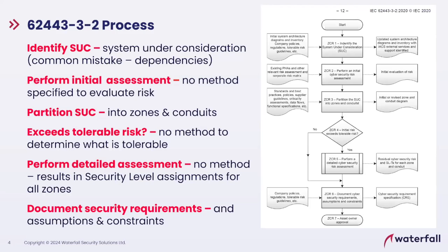Isn't it great? The problem is if the OT systems depend on the IT Active Directory, and the IT Active Directory is crippled in a ransomware or some other attack, we can't log into the OT systems anymore. Eventually, we've got to shut the plant down because we cannot operate it safely anymore. The automation is no longer accessible to us. And so the word here is dependencies.